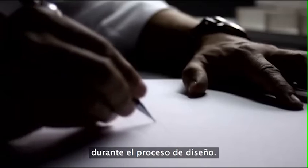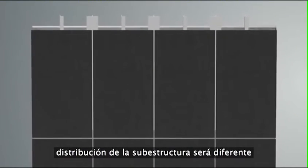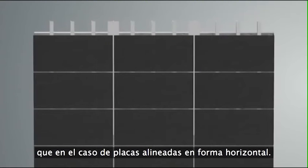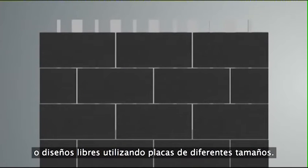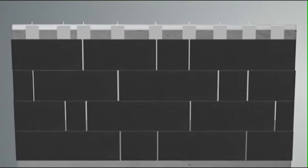The panel layout can have a big influence on the amount of large or small profiles needed. When meeting the architect early in his design process, it can be helpful to discuss this. For example, using the same size panel in a vertical pattern will result in a different subconstruction layout than if the panels were arranged horizontally. Other influences include having staggered joints or free patterns using different size panels.